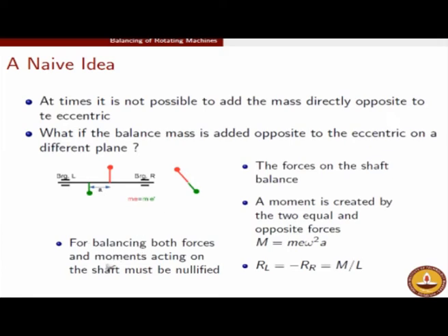So what we need is, remember, when we are talking about balancing, it's not just about the forces, it is also about the moments. It may feel to you that it is only the centrifugal force which is causing unbalance. True, it is only the centrifugal force, but to balance the system in totality, we need to balance both the forces as well as the moments.